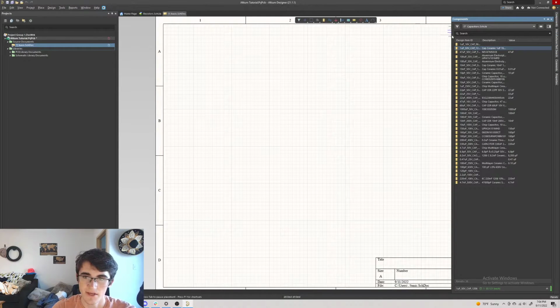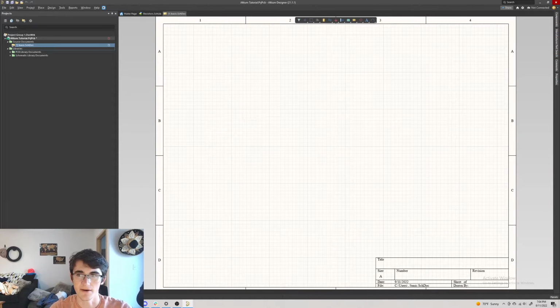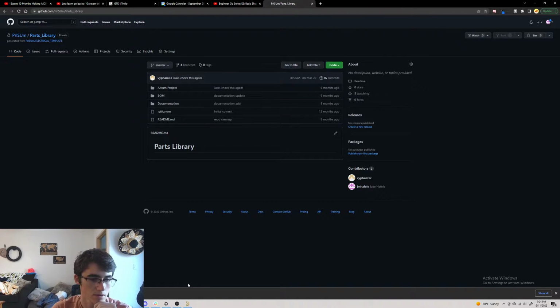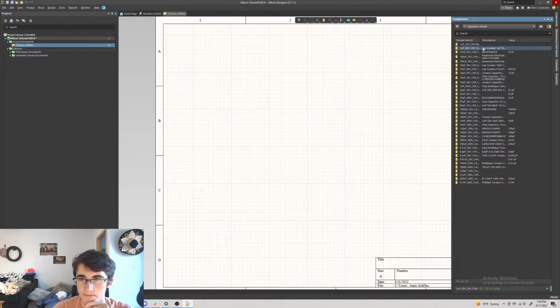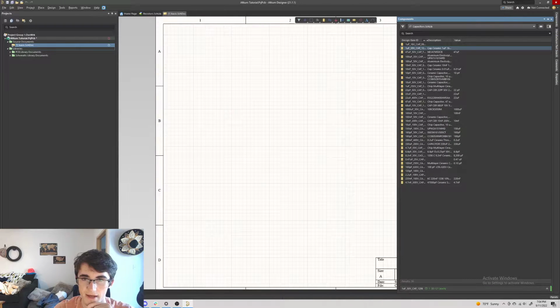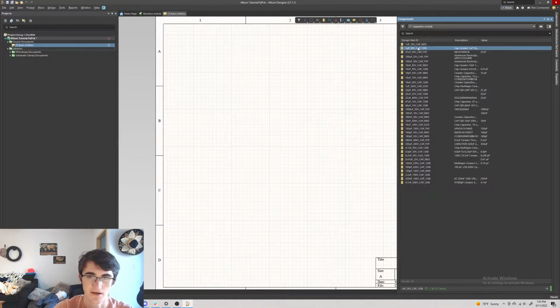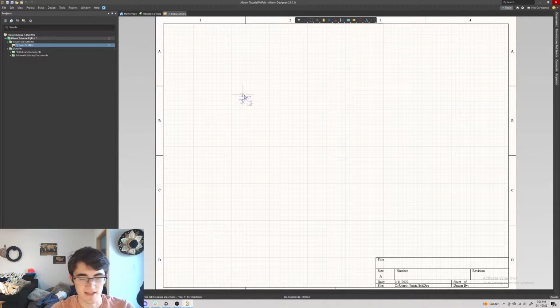So this part right here, you can expand this tab out and read about it. Stretch these out so you can see it's a 1 uF capacitor, max voltage at 50 volts, and it's a 1206 size. So say, cool, okay, maybe we want to filter a power line coming into the board, or maybe filter a signal going out. Cool. Now we can do that.